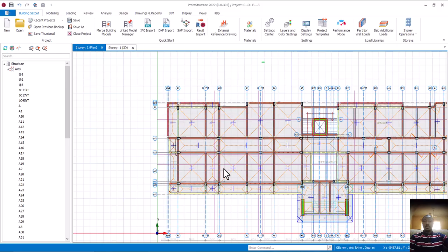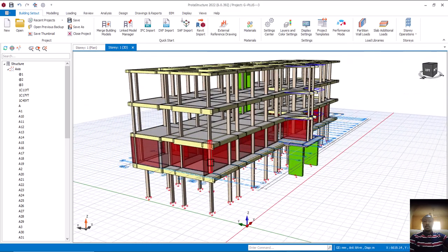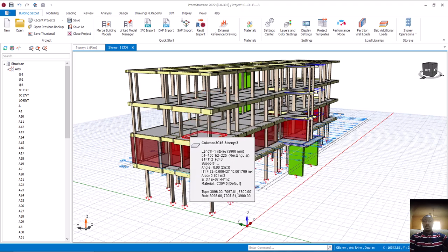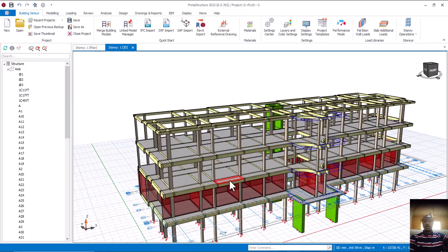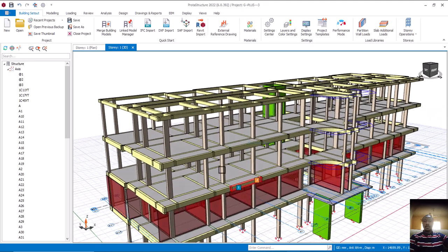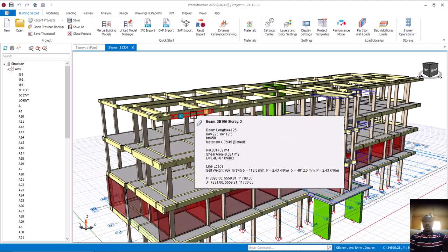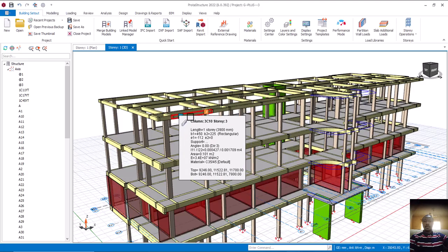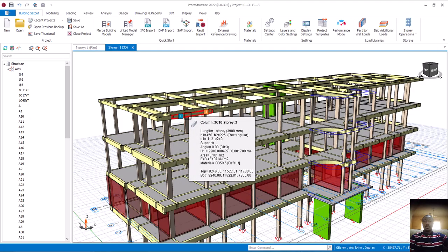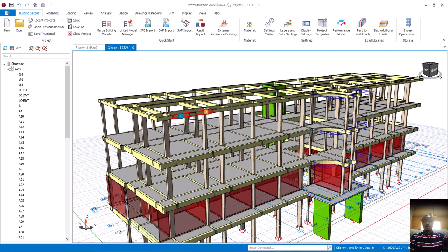Since this height, what we have here, is the same thing with this upper side, this particular one. Is that okay? Let me connect them now. But if I connect it, don't forget that the height here is different from here. The height here is different from the height from here to here. They are all the same, but because this one is the roof beam, I have reduced the depth of this beam. So if I use the same thing now, definitely there will be space.